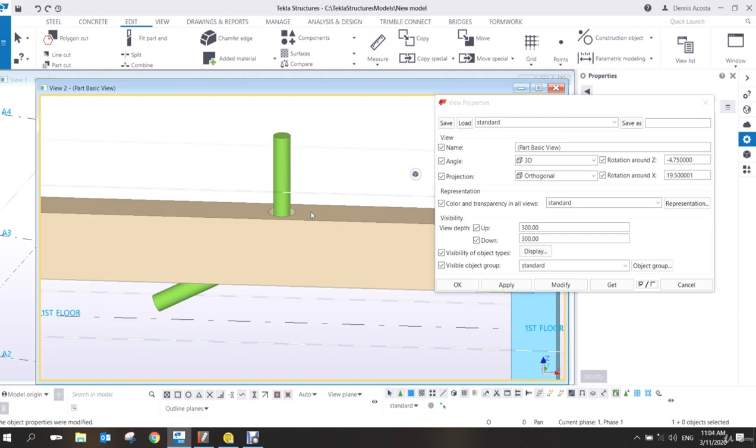But again, in this kind of situation, this one is difficult to insert if you have a smaller opening because of the curve. So meaning, in this case, they put the tube during the casting. So it depends. But if that one is the straight one, then they must have, I don't know, 2 or 5 millimeter erection clearance so that they can insert.